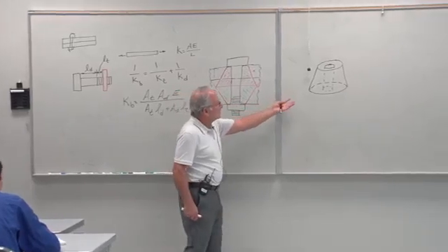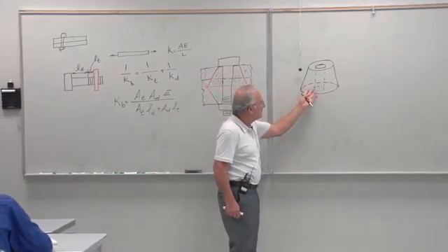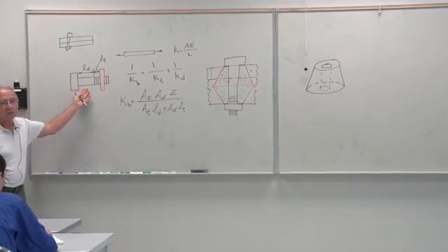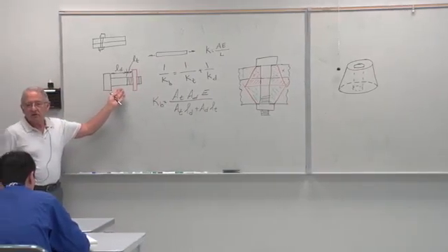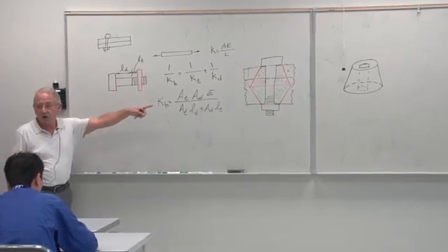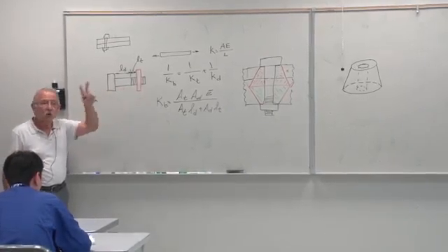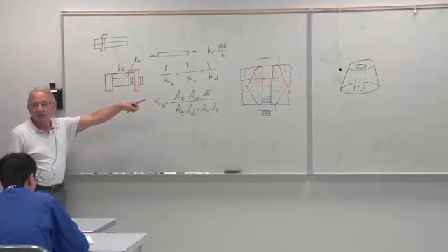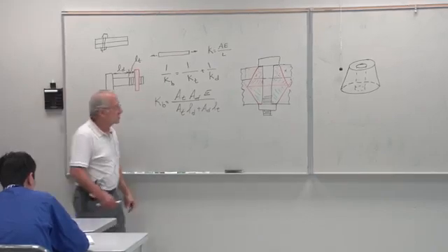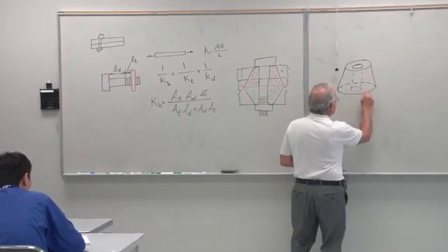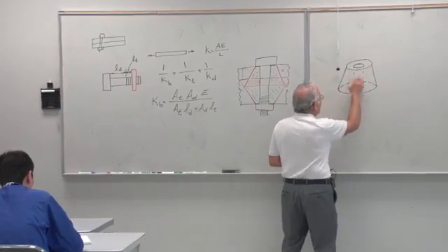And as we look at this, well, this is not very much different from this bolt. The only difference is, well, actually 2 differences. This is under tension, that's under compression. That's 1. 2, this has a constant cross-sectional area, that one does not. The cross-sectional area here that carries the load looks like this, all over. And it changes.